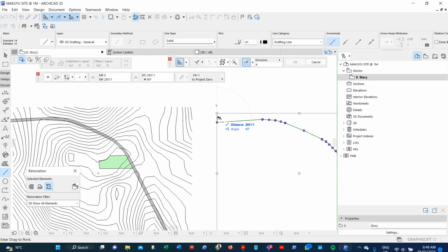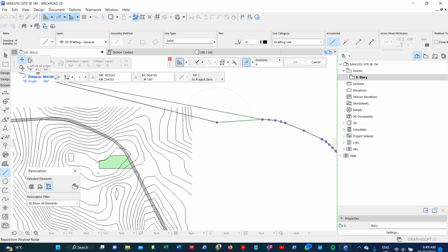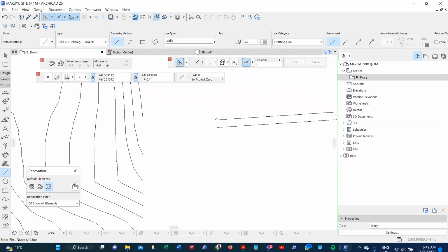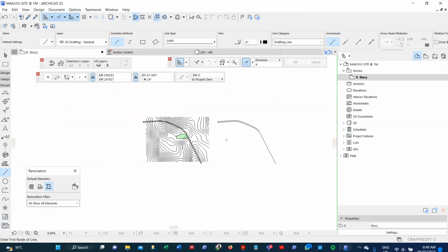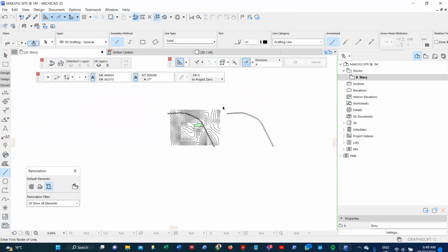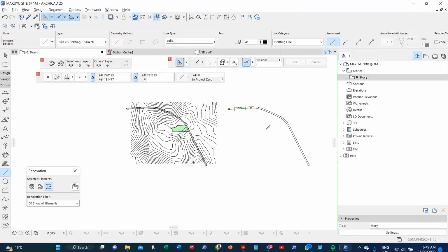And since I know that my road reserve is 12 meters, I can easily offset by 12 meters. Okay. Then come and top up there and there. So for now, I know that that will clearly give a better presentation of my road. So I can move it.